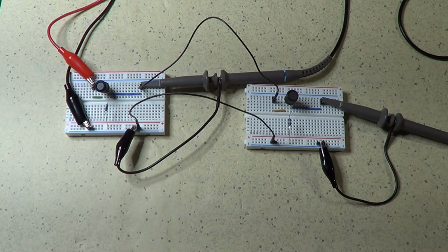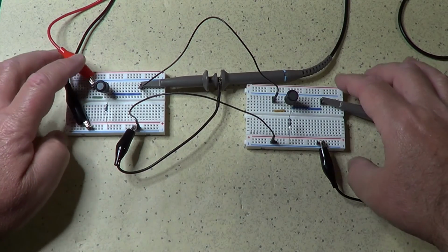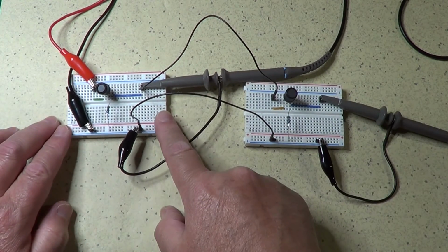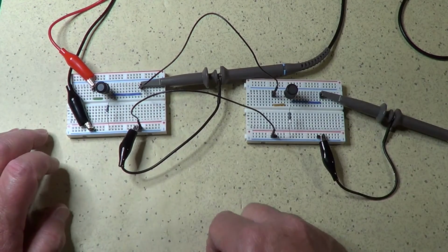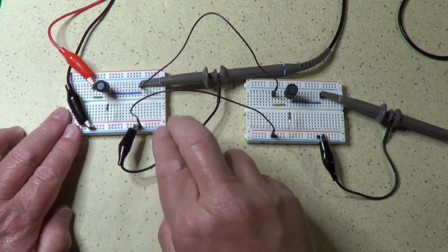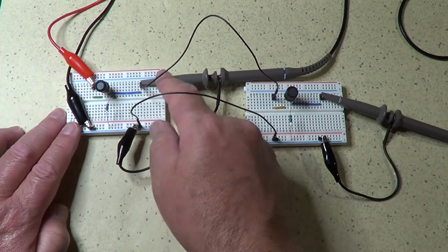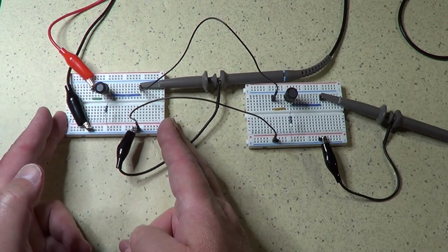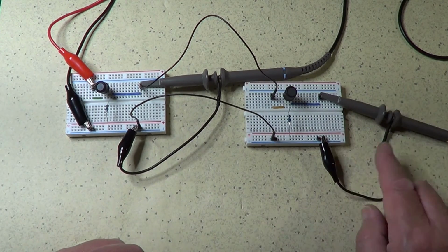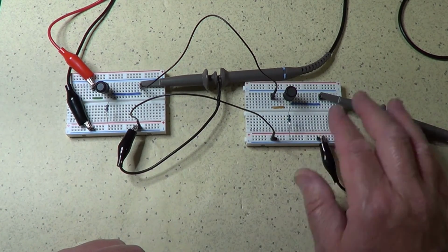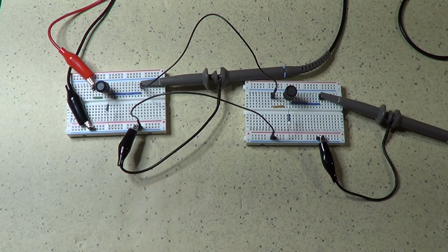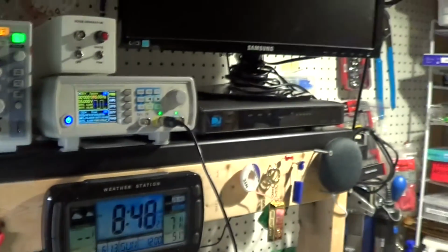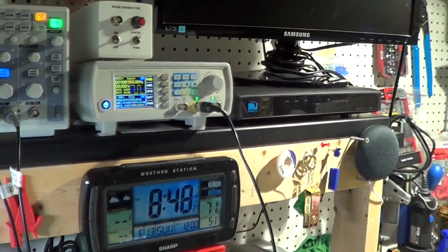So now, before concluding, let's take a look at one last case. Basically, in this case I have the two first order low pass filters again connected in series, but I have one channel of the oscilloscope, the blue one, connected to the output of the first order low pass filter, and the other channel of the oscilloscope, the yellow one, connected to the output of the second order low pass filter. Let's see what difference there is with respect to the response to a square wave, like this one here.